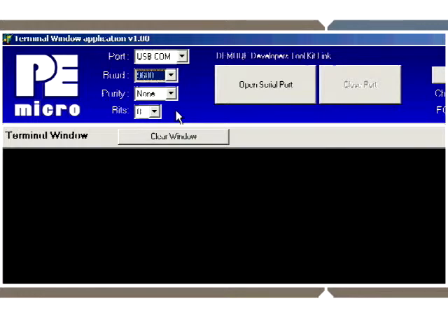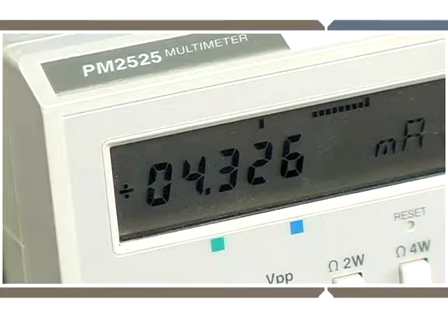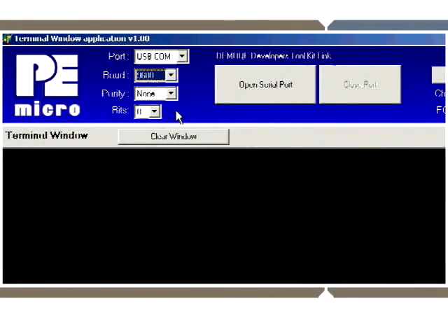At this point, the MCU is now running the low power application in normal run mode. We can note our normal run mode current on the digital multimeter and see that we have an LED blinking to let us know the part is operating. Back in the terminal utility window, click the Open Serial Port button, and we can see the device communicating with our terminal utility. As we observe the output, our count should increase by 5 every 5 seconds.